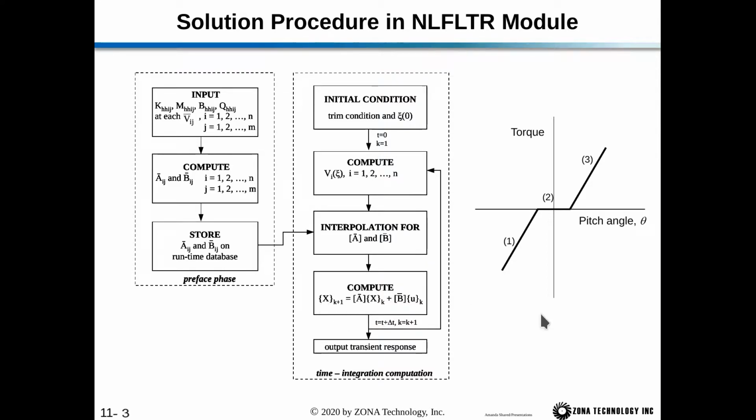So as an example of what you can do with the nonlinear flutter module, we can have an actuator with freeplay. Without freeplay, of course, the torque theta diagram would just be a straight line, but with freeplay, within the freeplay region here, our torque is 0, and then outside the freeplay region, we have the torque force. So with this example, we have 3 sublinear regions.